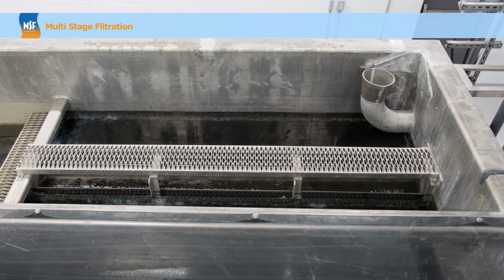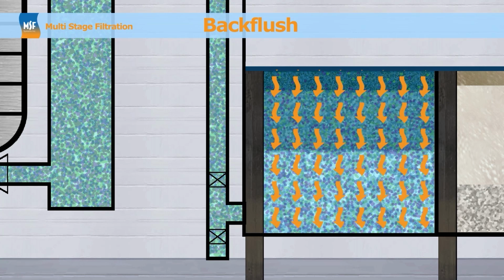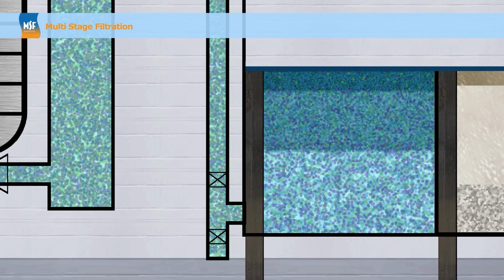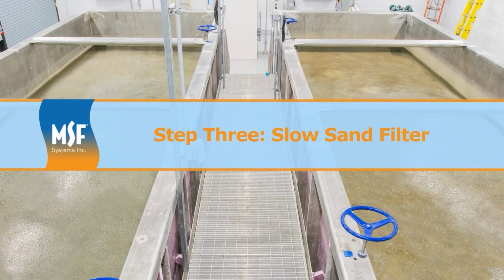The roughing filter is periodically cleaned by a backflush and an aggressive upwash cycle, dislodging and carrying away particles. This cleaning process is easy, yet essential to protect the biological life of the slow sand filter.